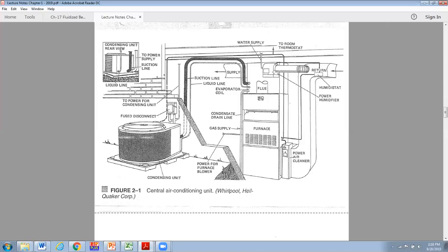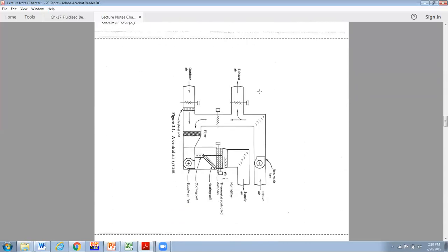We have a hard time maintaining moisture levels. So if you purchase a humidifier, we run a little water in there and it will inject water. It will probably have a little heat source to make steam and inject that into the supply air in order to maintain moisture levels during cold, dry weather. So that's a possibility.